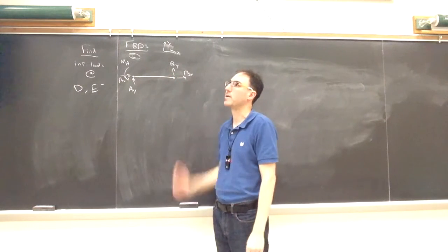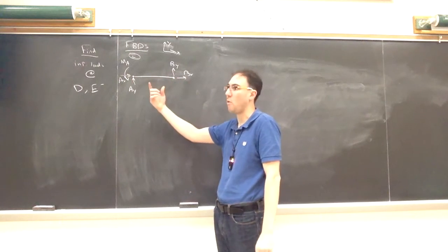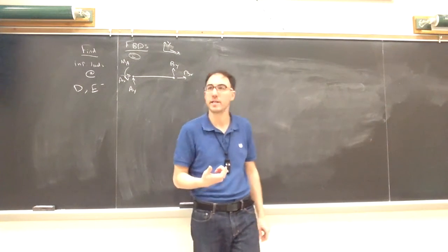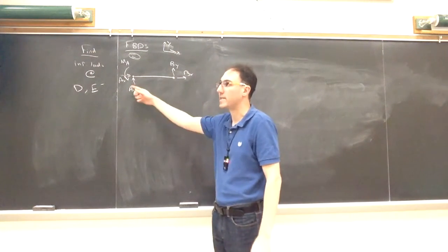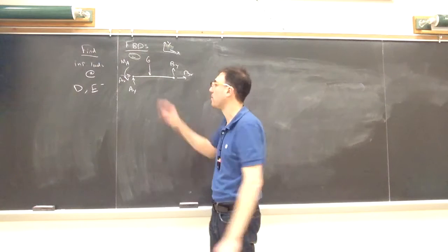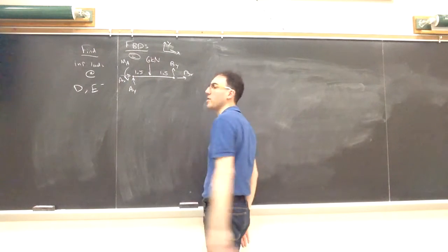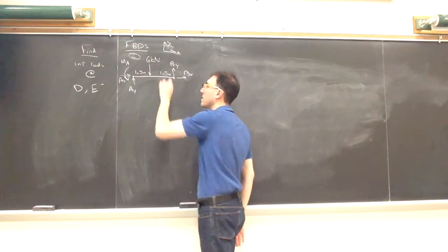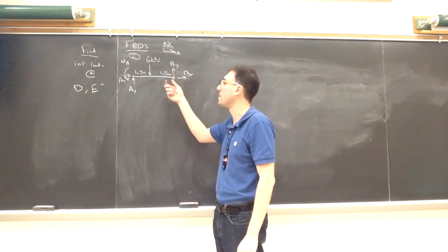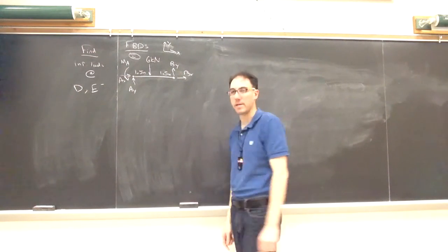So I have the external wall reaction, I have this connecting reaction with the pin at B, and then I also have a distributed load that acts from A to B, which in this free body diagram I can simplify like we did before to just a point load. It's a uniformly distributed load with a constant intensity, 2 kilonewtons per meter, and it acts over the entirety of A to B, which is 3 meters. So this is equivalent to a 6 kilonewton load acting in the center, 1.5 meters from either end. We'll come back to that topic of distributed loads when I get to the internal picture here, but we'll start with this. So externally, this is what this beam is going to look like.